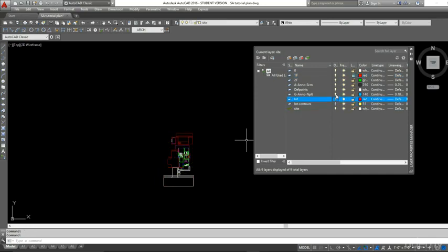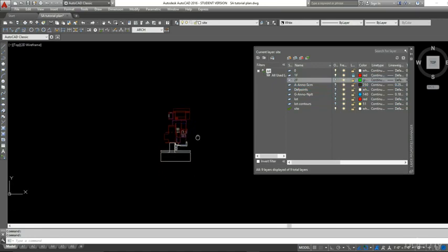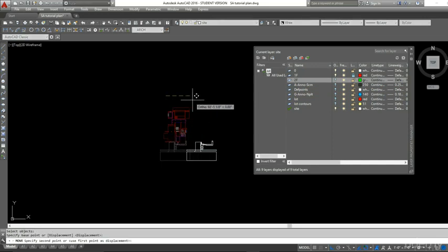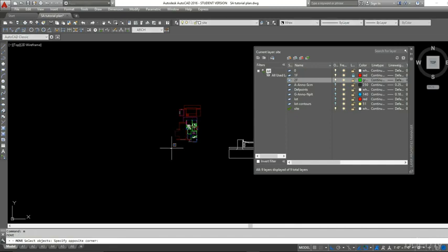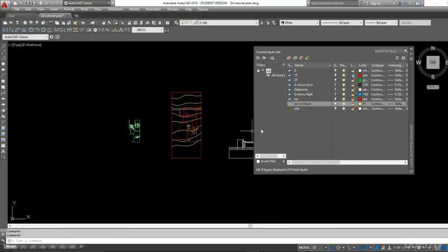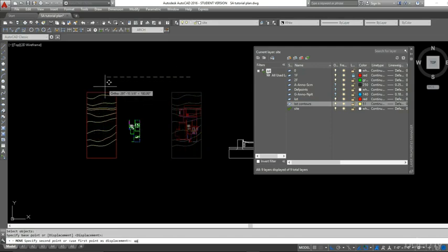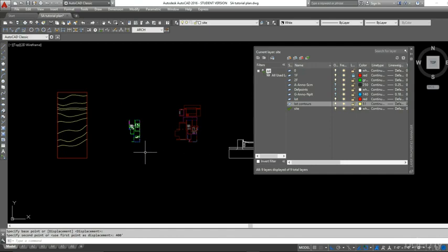and I'm going to shut off all these other layers, and let me turn on ortho mode, and I'm going to move this over to the right 200 feet. Now let me turn on my second floor layer 2F, and I'm going to move this over 200 feet to my left. Now let's open up our lot and lot contours, and I'm going to move this over 400 feet to my left. Now let's unlock this layer.